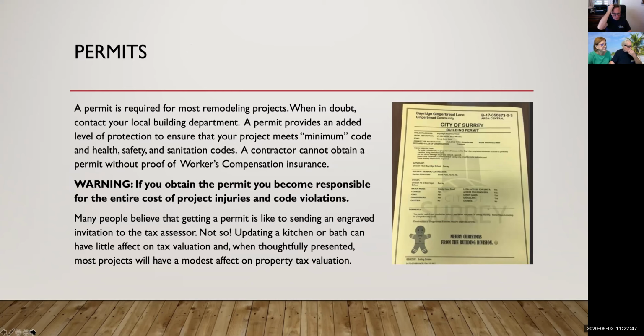Permits, that's an important aspect of any project. I will tell you that a permit is required for most remodeling projects. When in doubt, though, contact your local building department, your building officials. A permit provides an added level of protection to ensure that your project meets minimum code and health, safety, and sanitation codes.